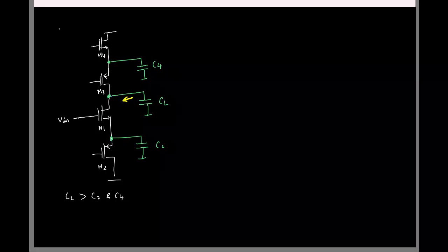And when you do that, what will you do to these capacitors? Why do you open them? Exactly. What's a dominant pole? As you know, it's the lowest frequency pole in the circuit. And I already mentioned these capacitors are very small. A small capacitor at low frequencies is as good as open. So we can open these. So the impedance looking into CL is the output resistance you computed before, and that gives the pole location. So that was Rout times CL. That's all.